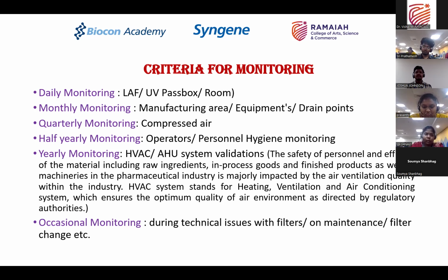Then there is something called occasional monitoring. Now, what is meant by occasional monitoring? If the laminar airflow filters are not used, or they are not working, during maintenance, or during the change of the filters, all this monitoring is called occasional monitoring. So in an industry, different areas will be monitored for viable and non-viable counting on different bases. What are those different criteria? It can be daily, monthly, quarterly, half yearly, yearly, and occasional monitoring.